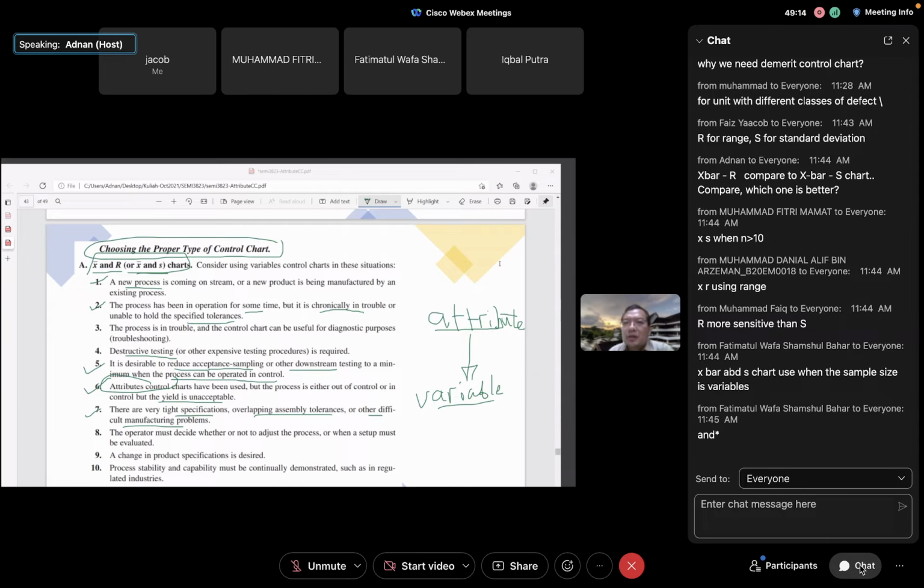The dispersion can be monitored as range or as standard deviation. Dispersion refers to how spread out, the repeatability. It might be accurate but not repeatable. We want it precise and accurate. That's the best.